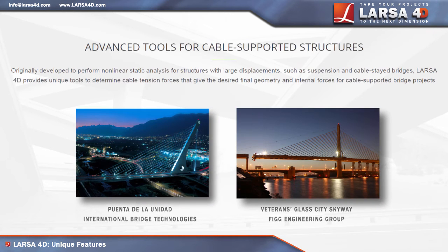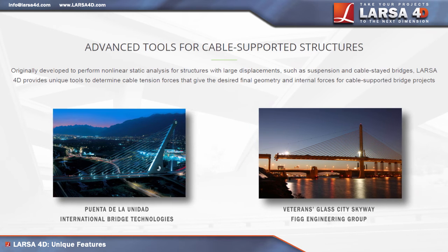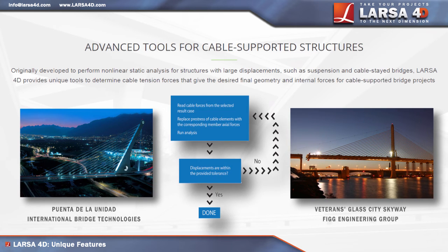Extensively used on cable-supported bridges, LARSA uses optimization algorithms which help find the cable forces to give the structure its intended final geometry. When working with post-tensioned cables, LARSA's post-tension load iteration process will force the rest of the structure to adjust in order to keep the cable force constant within the specified magnitude, simulating the jacking operation at a constant force of a cable.